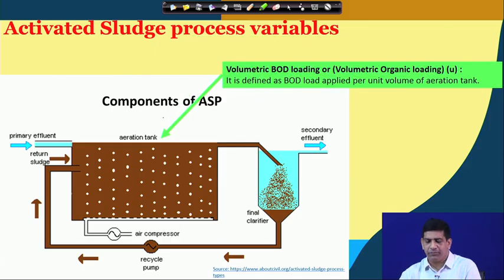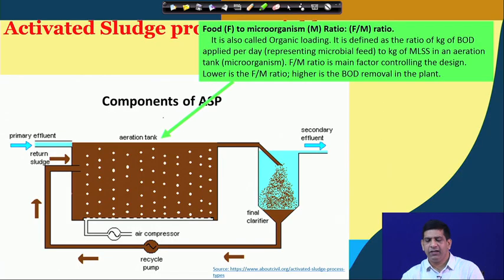Based on that we can calculate how much flow is coming in. So, we know how much BOD is coming in. We talked about the BOD, biological oxygen demand. So, why is BOD important? Because based on the BOD we need to have the microbial population to degrade it. More BOD means more organic matter, which means more microbial mass needs to be present.